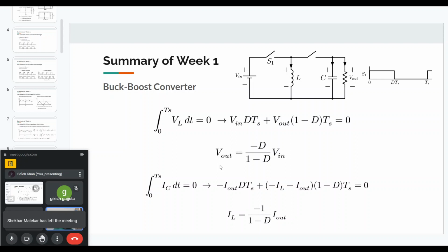Further, you can do a lot of things. You can then find out what the voltages and currents through these switches will be. And based on the polarities of these voltages and currents through the devices, you can see whether the switch that you require is a one quadrant switch or a two quadrant switch, and in which quadrant it lies. And based on that, you can select a diode, whether a diode is sufficient or whether some other kind of device would be needed.